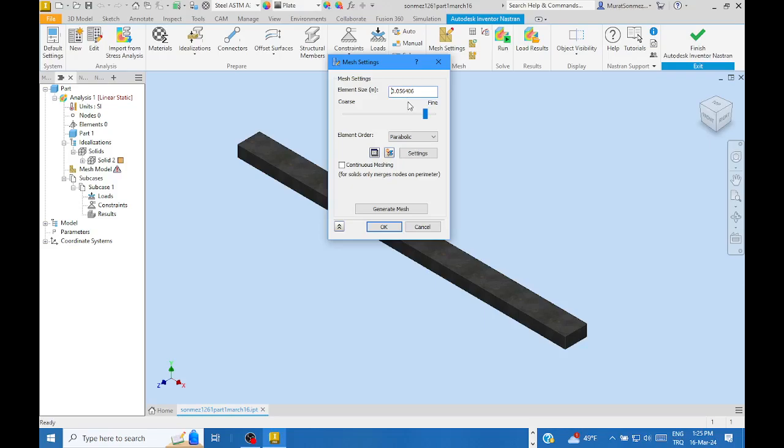That is in the default setting, not a fraction but the size of the element, the average size of a finite element, say 56 millimeters. Well, there's an adjuster here, a slider, to increase the number of elements to have the solution more accurate, more precise. Slide it to a finer mesh size. But be aware, if you do this, runtime may be very great, and your computer may not be capable of solving that problem. Okay, be aware.